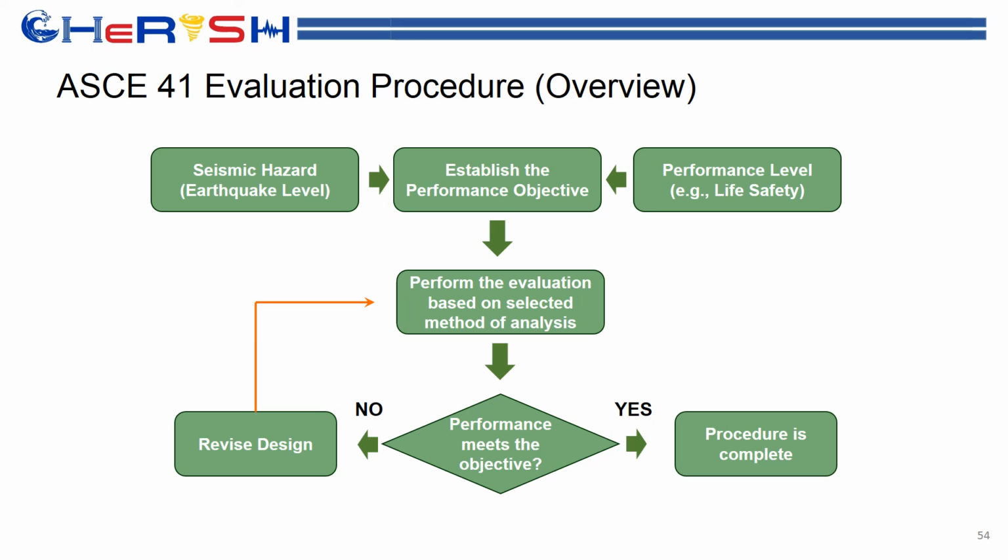Then you evaluate your building based on that selected performance, and you assess if that performance is met. If not, you can revise the design or do some retrofit. Whereas if your building passes the assessment, then the evaluation is complete, and therefore you were able to meet that performance objective. The flowchart looks simple, but really there are some details involved inside this methodology.